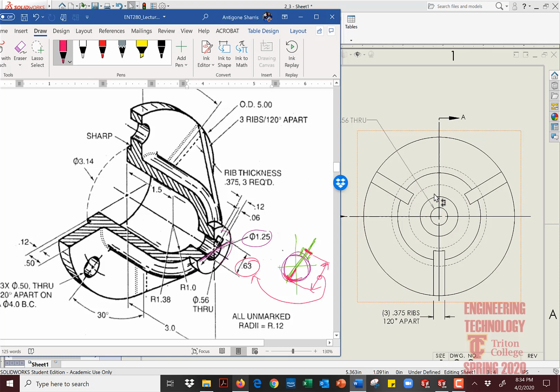That's why we hand sketched it right there. If we were in class together, that's what I would ask you to do, is hand sketch it, because if you can't hand sketch it, you're not going to be able to sketch it in CAD, because CAD does nothing for you. You have to know what you're hand sketching here in order for you to be able to duplicate your activities in here. So with this in mind, now the width of this, remember all this information, we're going to assume, we're going to offer 125 because we're going to ask, remember that, ask. Okay, and this half dimension here is going to be a 1/16 of an inch, because half of an 1/8 is a 1/16.